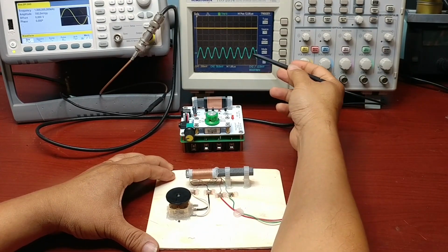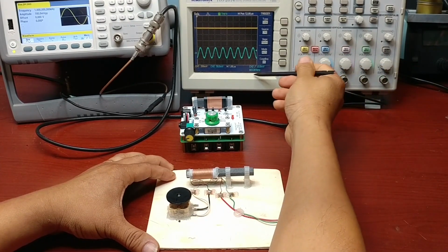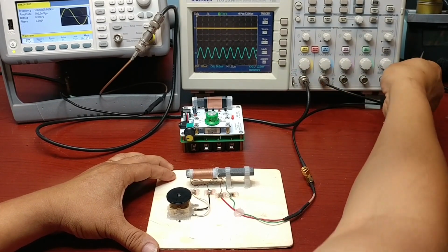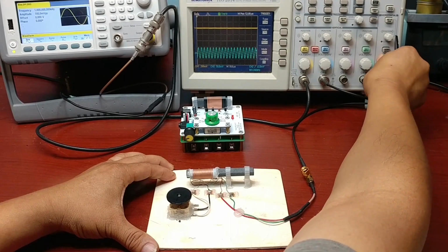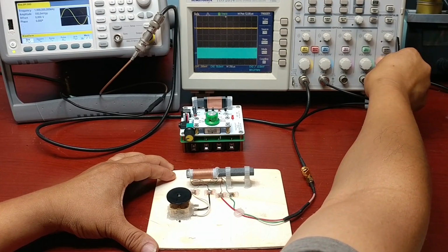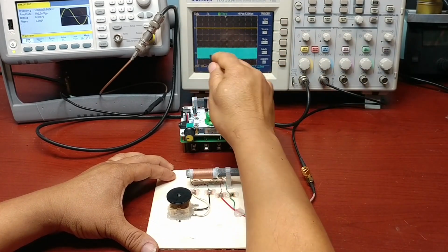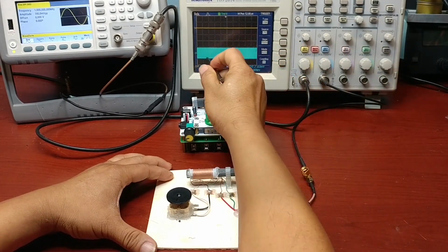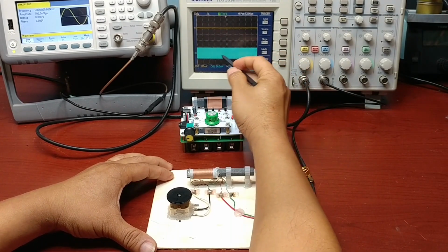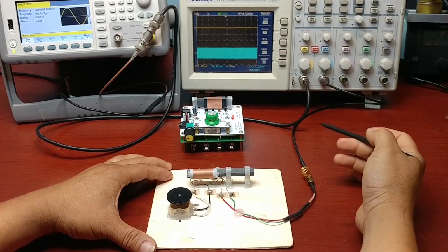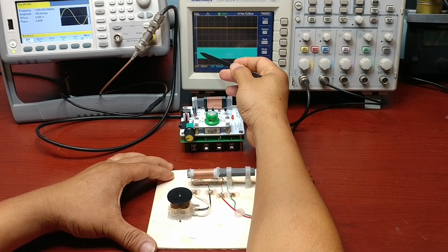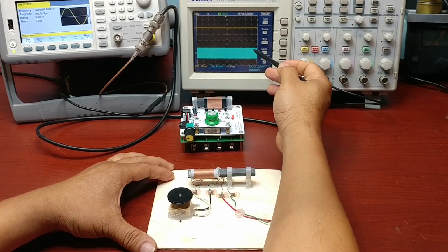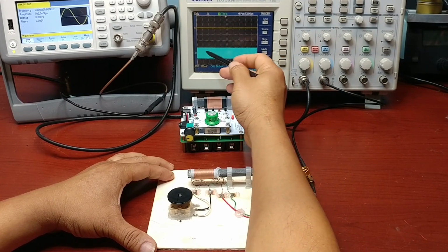This is a sine wave signal. We can read 803 kHz here. If we look at the signal in a bigger time window, the signal looks like this. The inside is a carrier frequency 800 kHz sine wave. The amplitude of the signal is flat and unchanged. The outside border is the envelope of the signal.